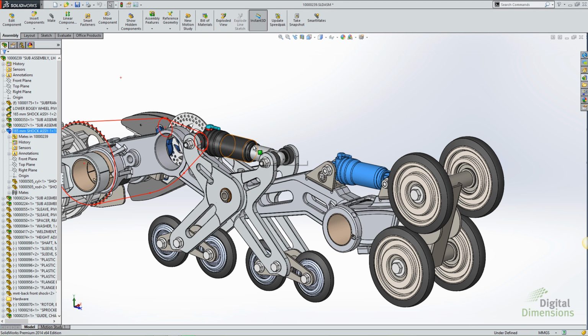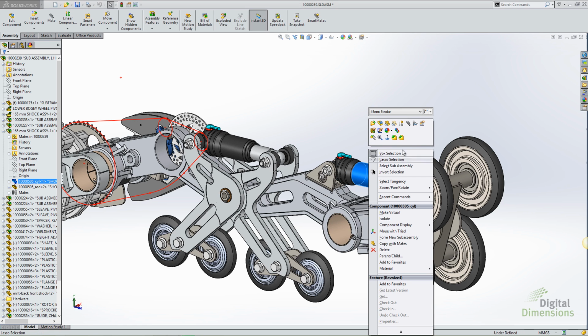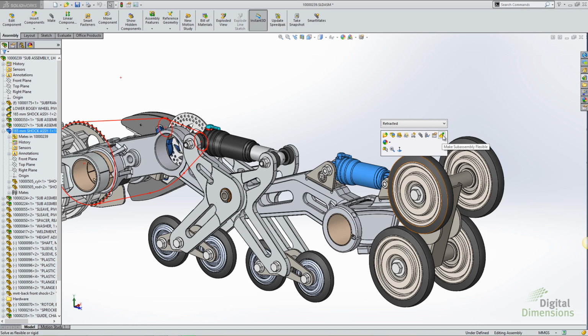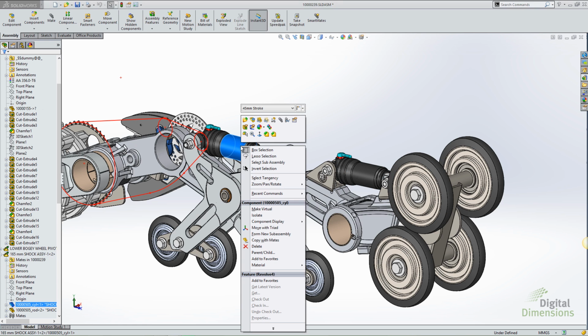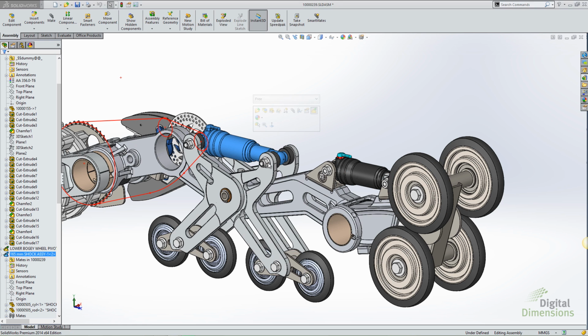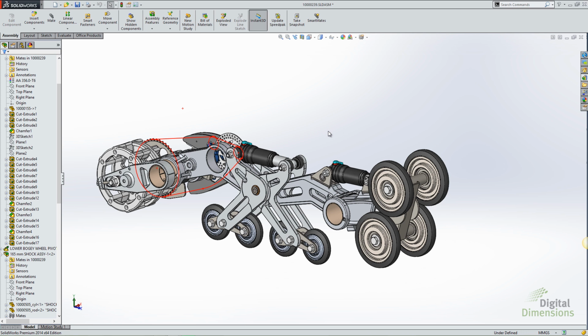I can also select whether the item or the subassembly member is rigid or flexible. Enhancements in the way that flexible subassemblies behave have also been made in SOLIDWORKS 2014, to where two separate instances behave genuinely independently of each other.